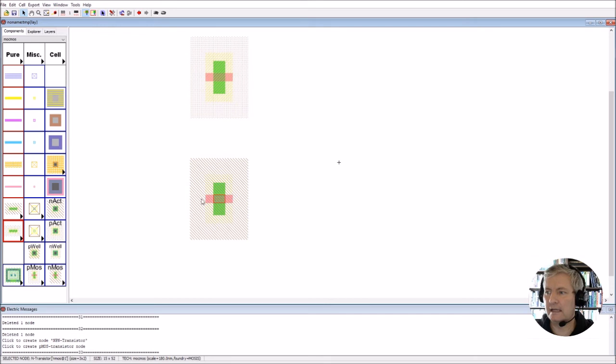And this is the gate here, which is in pink. Now for the PMOS device, we're going to have a PMOS existing in an N well. So this is the N well on the outside, and it's all little dots, okay? And we've got the active region here, again, which will be the area underneath the gate, and this is the gate here in pink.